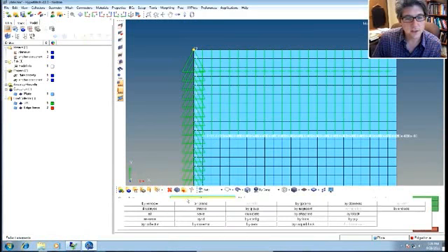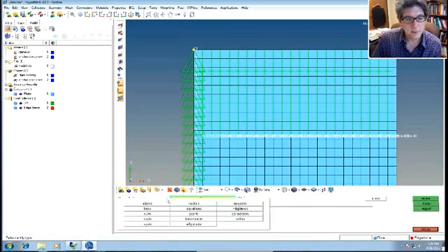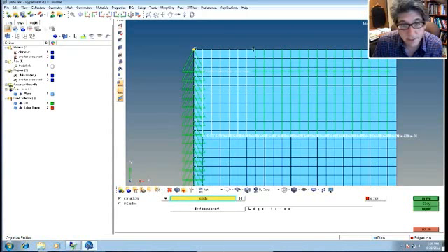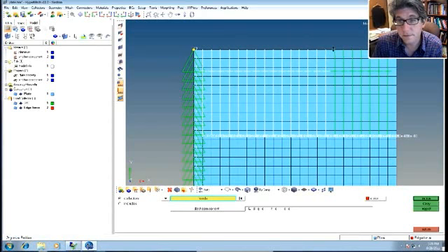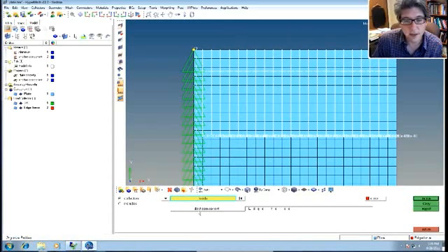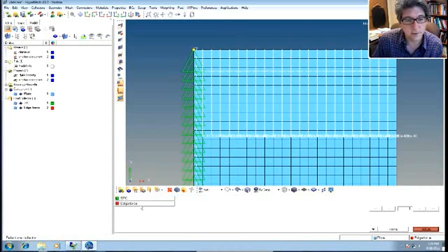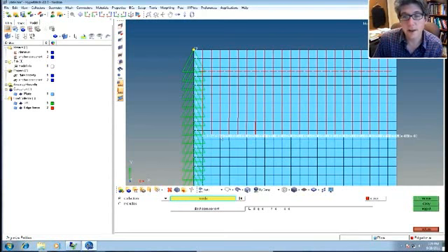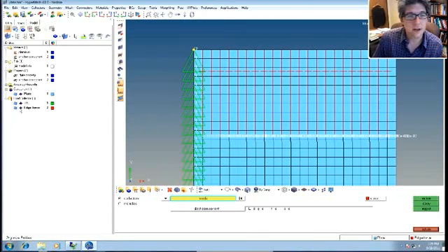Okay? So let's change this, because we don't want to pick elements, we want to pick loads. So now I can go and select the nodes, and you have to actually pick the little tips of the arrows. Pick them all. So those are the ones we're going to move. And then we're going to select the destination component to be edge force. Probably already selected it since we made it current, but okay. And now we're going to move. We don't want to copy, we're going to move. Now you can see they all turned red, they're happy. Okay? So that means they're on that level, right? Okay, toggle them on and off.